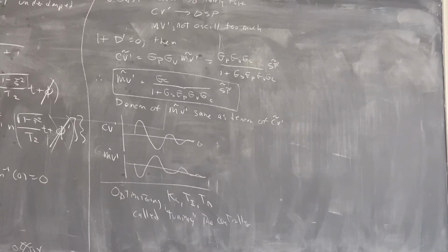Instantaneous doesn't mean it happens in 0 time. It means compared with the time scale of everything else, of the process and of the measurement, and of GD, GS, GP. Notice, GP and GD have time scales in them. The time scale of the computation is much, much faster than the time scale of the process.